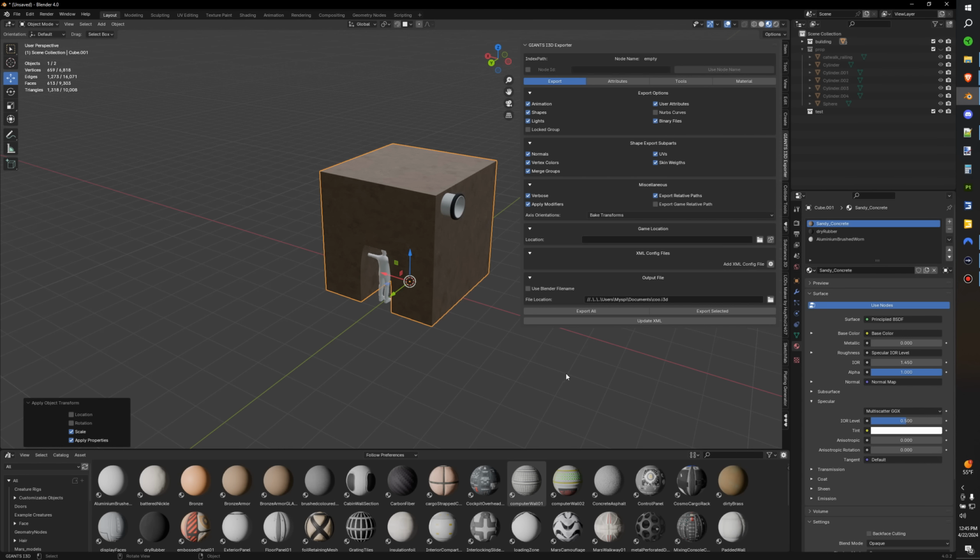You'll see an error, could not do this. And sometimes it tells you what was wrong, sometimes it doesn't. If you can't figure it out, try to export fewer objects. Don't try to export a whole car with the wheels. You might run into a lot of issues that way. Just try to do it piece by piece or in sections. That way, if you encounter an error, you can fix it.